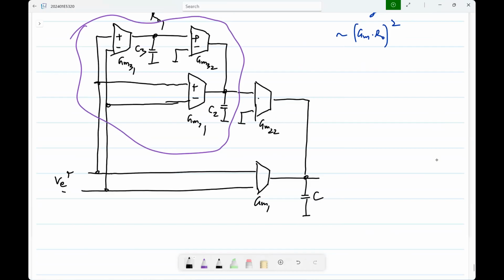So again, I am sure that you can sit and analyze the poles and zeros of all this. But roughly speaking, what will be the order of the DC gain? Which is the dominant path for the DC gain? The one with 3 stages in cascade, right? So basically this goes through this, gives you one GMRO, another GMRO, another GMRO. So you get GMRO cube and you can keep going.